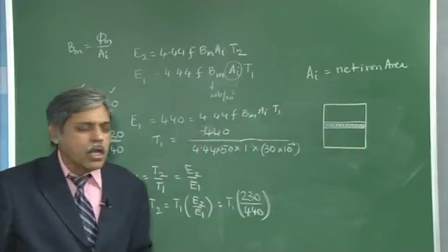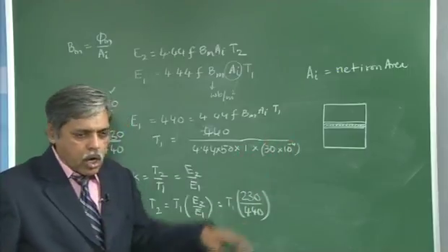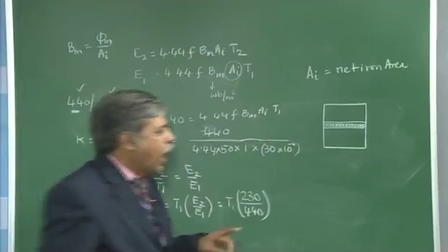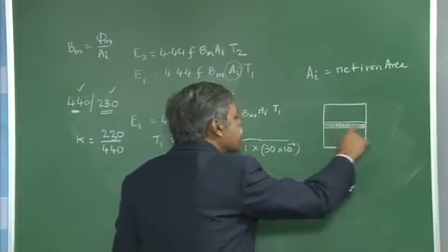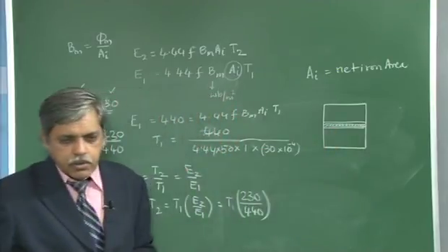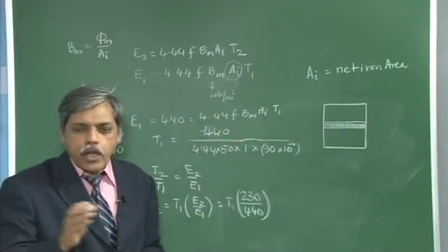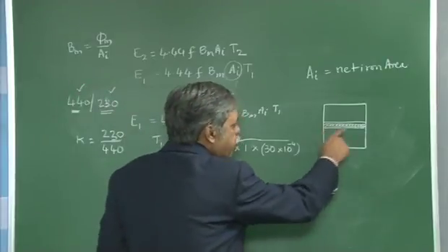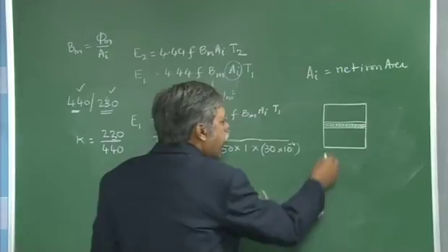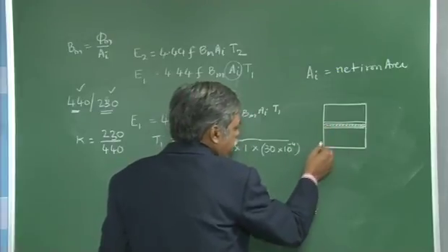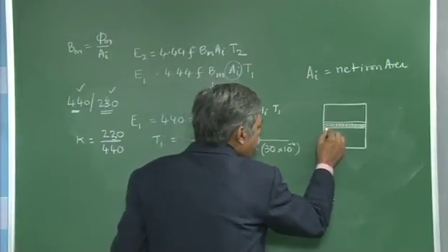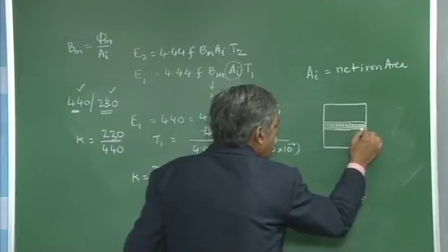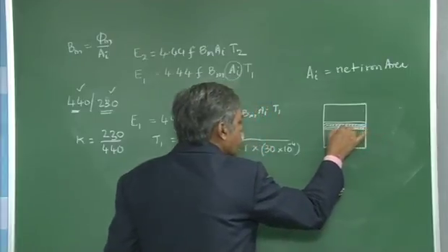So, generally in constructing or assembling the core, I take thin sheet steel laminations, provide a varnish coating on that, and then stack the next lamination. Like that, between the two laminations I always have an insulation coating.